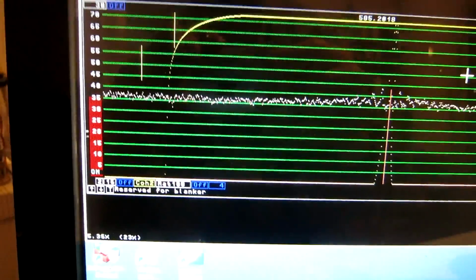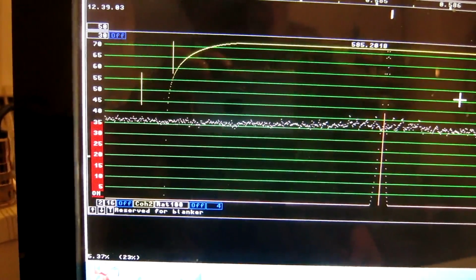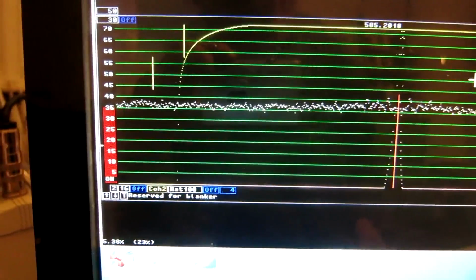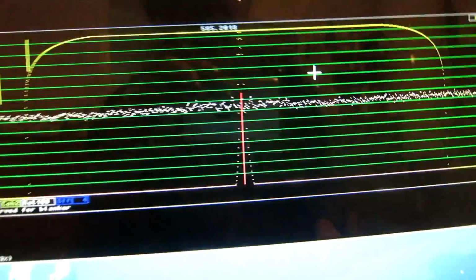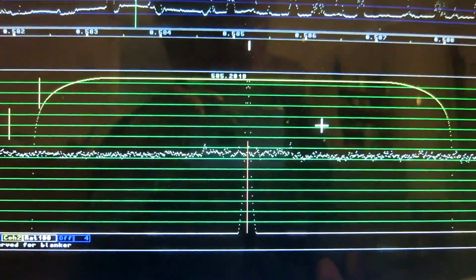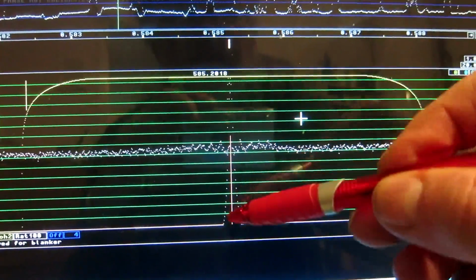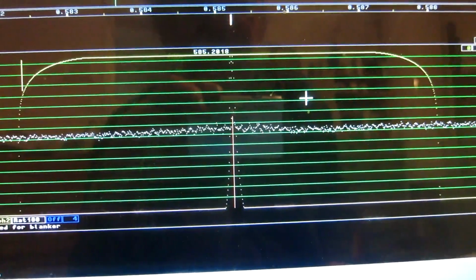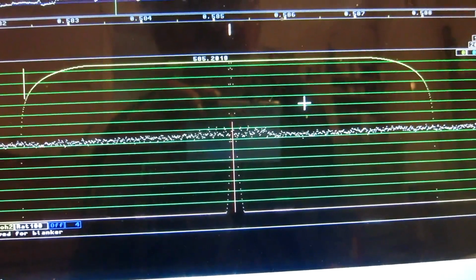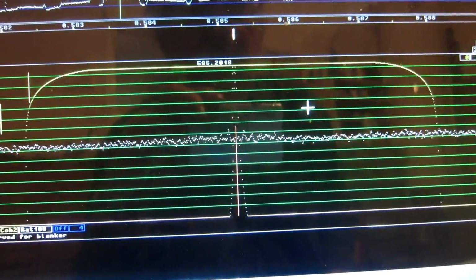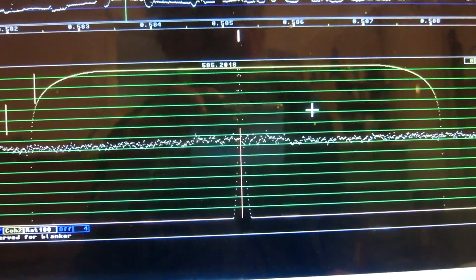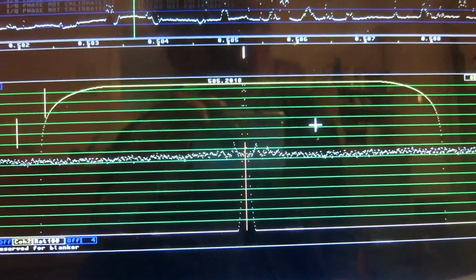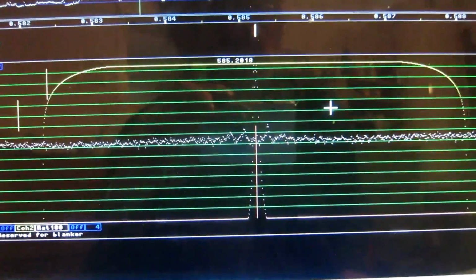I have now changed the transmitting instance of Linrad to coherent mode 2. There is a narrow filter, this filter, that selects the carrier, and then it takes the in-phase and the out-of-phase component with respect to that carrier and sends them as 2 channels onto the network. On the other computer I received the 2 channels.